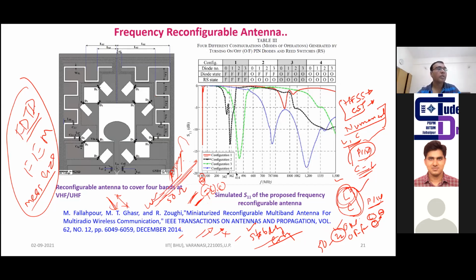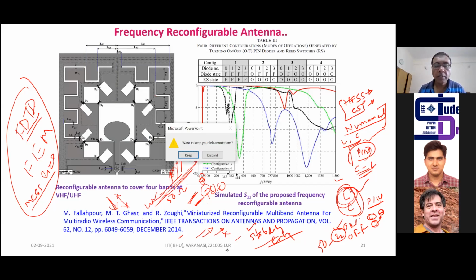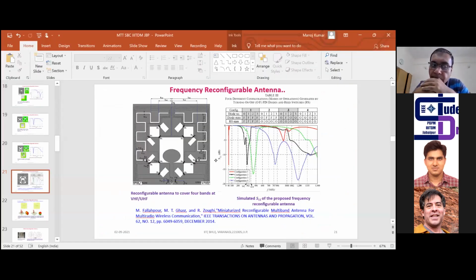Okay, for the time being, Manoj. One more question, sir. I'm concerned about the D1 square, the large square in the center. How is it not coupled RF, regardless of the diodes, to the D2 squares? It seemed to me that if the D1 square is energized or excited by a 400 or 500 megahertz signal, the D2 squares will be radiatively coupled. I don't understand how the pin diode will stop that.